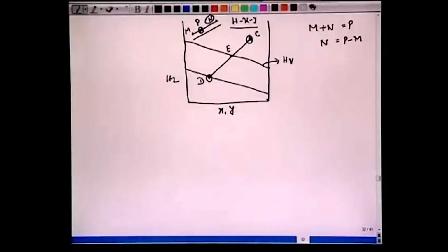So similarly here, one can say that this E, saturated vapor, is nothing but mixing this saturated liquid D and superheated vapor C. Or C is produced if we remove this D component, the fluid of this specification D, from E adiabatically.